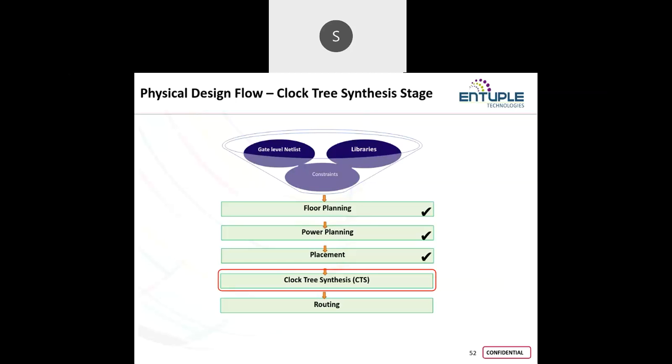Again, I am doing further work with the clock tree synthesis. There again, I am adding some cells for building and balancing my clock tree. So at that time, again some cells are added into the design, and then again the power consumption will change.